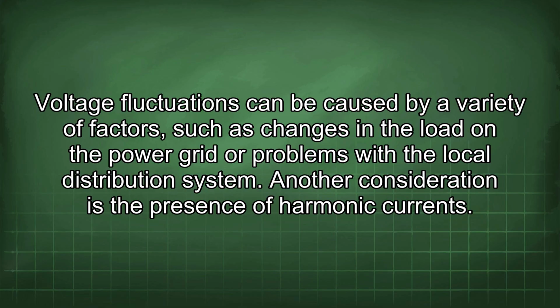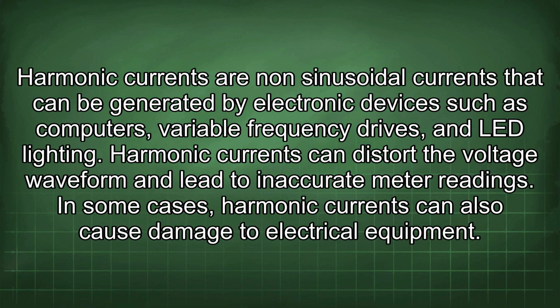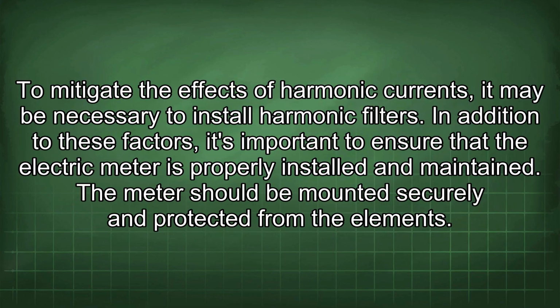Another consideration is the presence of harmonic currents. Harmonic currents are non-sinusoidal currents that can be generated by electronic devices such as computers, variable frequency drives, and LED lighting. Harmonic currents can distort the voltage waveform and lead to inaccurate meter readings. In some cases, harmonic currents can also cause damage to electrical equipment. To mitigate the effects of harmonic currents, it may be necessary to install harmonic filters.